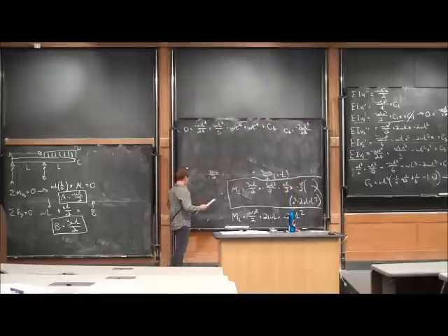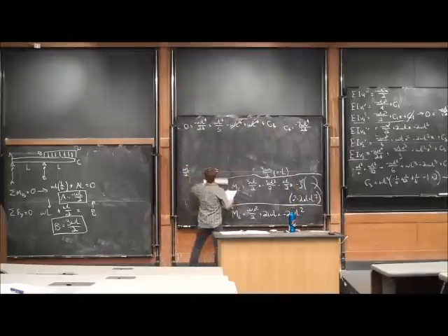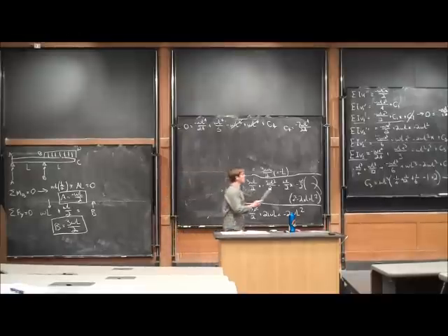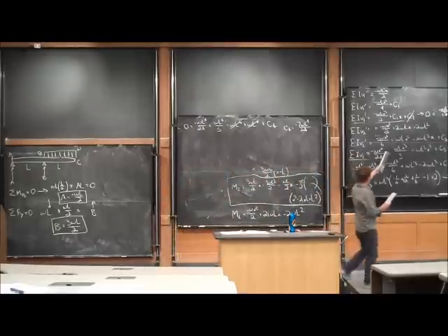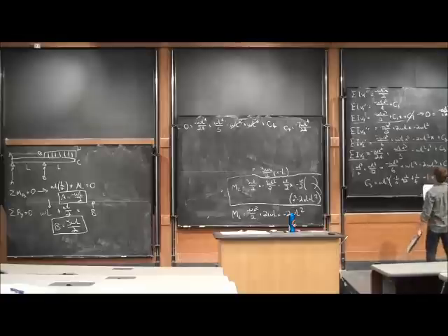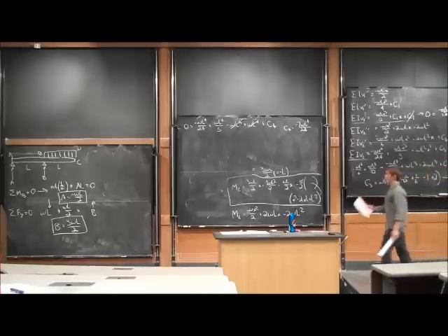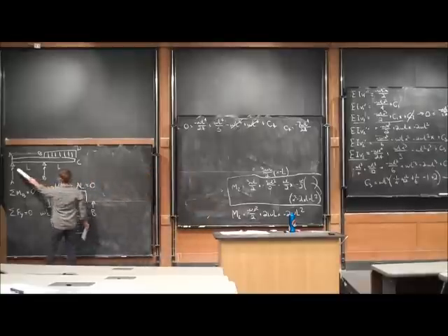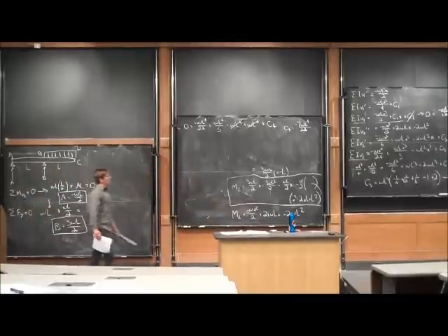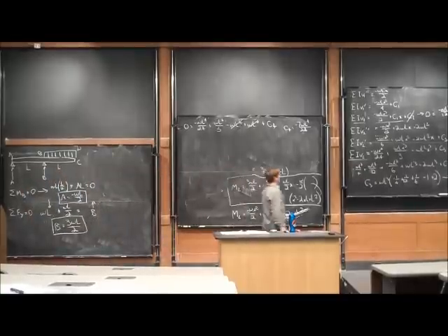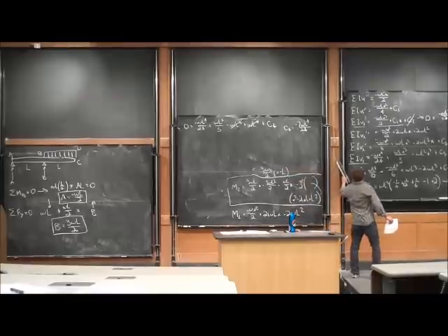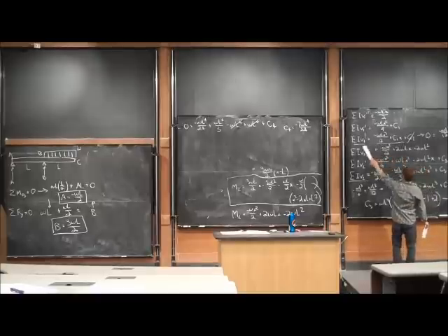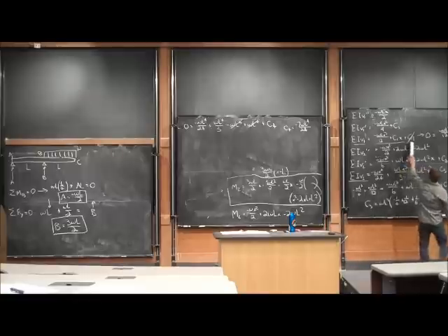So now that we solved all of our equations, we can then write what the deflection is. Where did we solve what C2 was? We saw that C2 was 0 at the very beginning because, I guess I already erased it. We recognized that the deflection at 0 is equal to 0 for V1. So that's where I solved it right here. Here was my V1 equation. I plug in x equal to 0. That term went away. That term is equal to 0, so C2 had to be equal to 0.